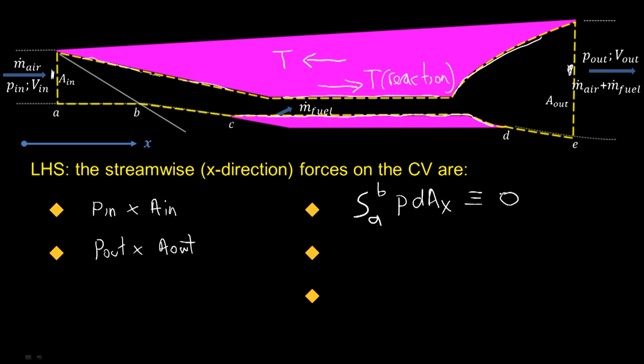Now, however, from B to C, we can notice that the line on the edge of the control volume is not now aligned with the x-axis. And this is because the flow has been turned by the forebody shock. Now this term, similarly, is the pressure times the component of the area normal to the x-axis, is not 0 unless the engine has full capture.